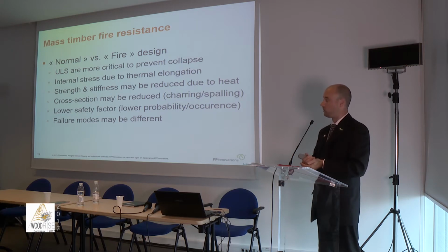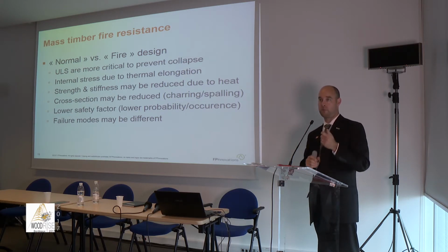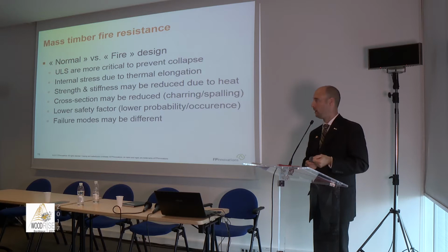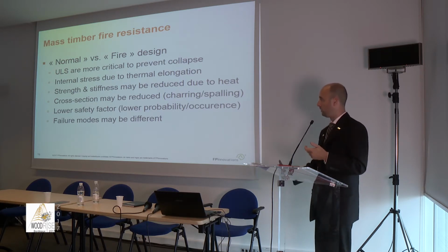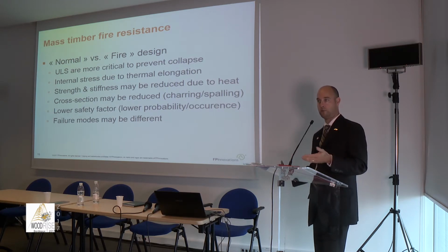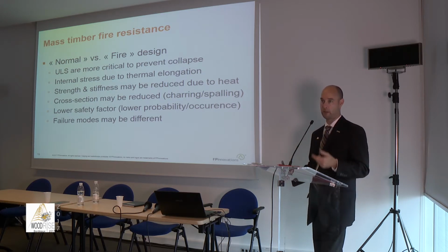For the structural engineer, one important thing to understand is that there are significant differences between normal design and fire design. Usually the ultimate limit states would be more critical in fire, so it will be the strength that will govern. Typically in wood, floor vibration or floor deflection might govern as opposed to strength. Steel walls might be governed by strength, and then in fire they might also be governed by their capacity.